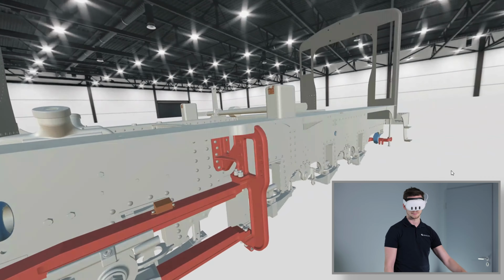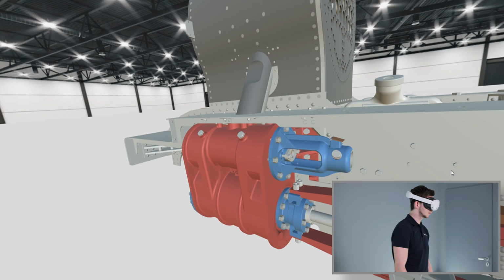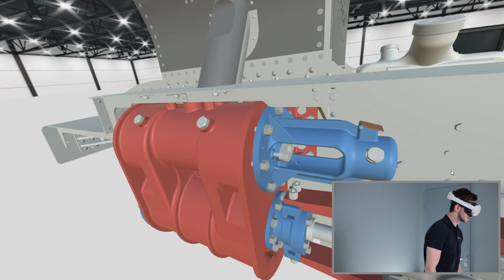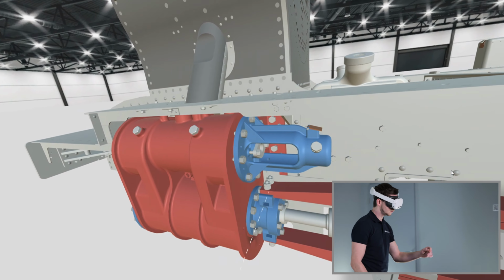To be able to perform a correct design review, one of the most important characteristics is to be able to load your CAD file in scale 1:1 in order to identify design flaws and see every possible defect or mistake in the project itself. During a design review, one of the very challenging tasks when you're working with a very complex model is to be able to look inside the specific parts without disassembling them.